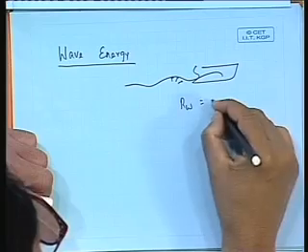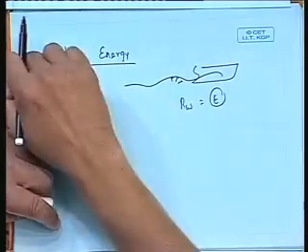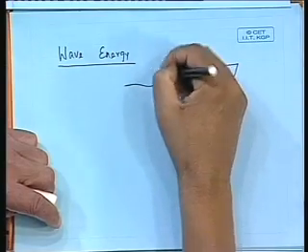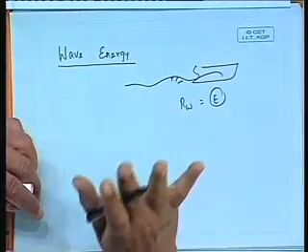Here is why I say this: the wave resistance can be related to the wave energy. If you could find out the wave energy of the waves, you can figure out the wave resistance part of it, because they are intimately connected. The amount of energy that has gone in, the amount of work that is done, gets spent as the energy making the waves. So if you could figure out the energy of the waves, then you could find out my wave drag. In fact, this is a classical way of wave analysis in finding out the resistance. So I need to know wave energy in some way.